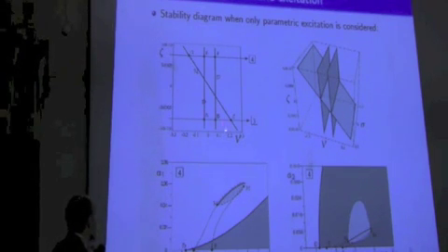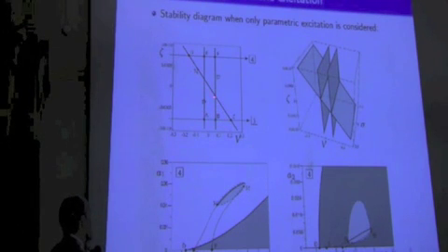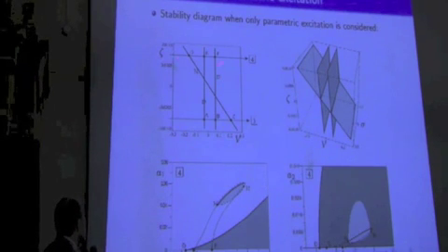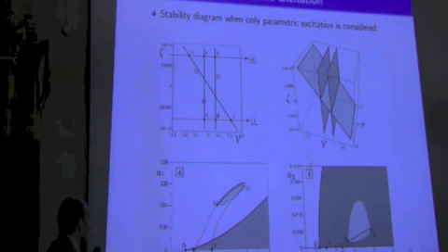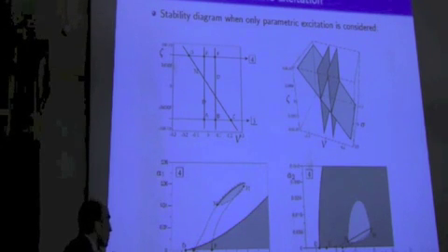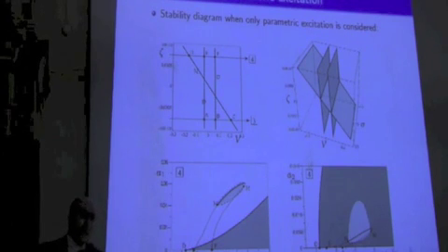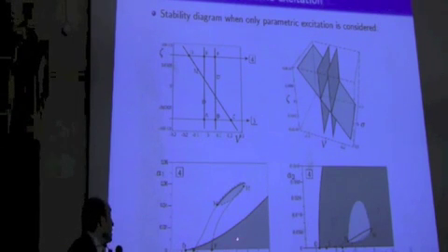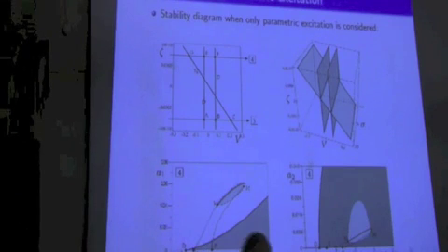Here we have, on the other hand, a Hopf bifurcation diagram, and if we follow a path here, for example, in this way, you can see the steady solution here, which closes at two bifurcation points, and moreover you can see periodic solutions in terms of the amplitudes. It means that here the towers are oscillating in a quasi-periodic fashion.